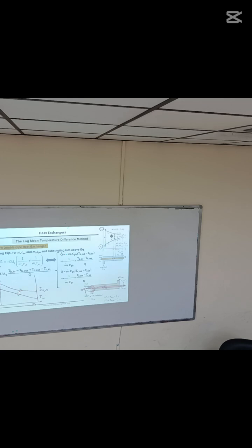They will never be equal, the TH and the TC. Look here, TCO may be greater than THO. That is the main thing. In parallel flow, TCO can never be greater than THO; it will always be lower than THO.